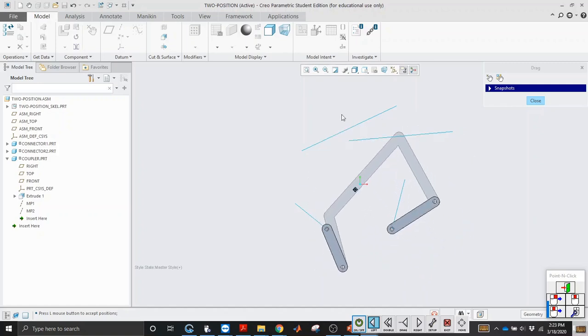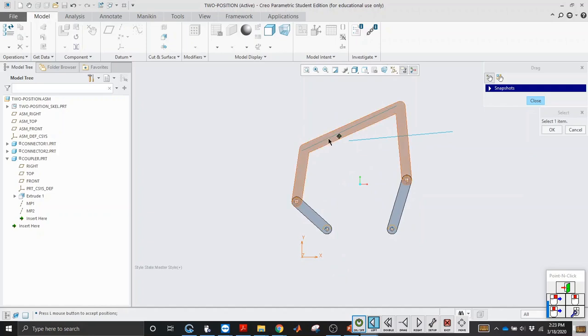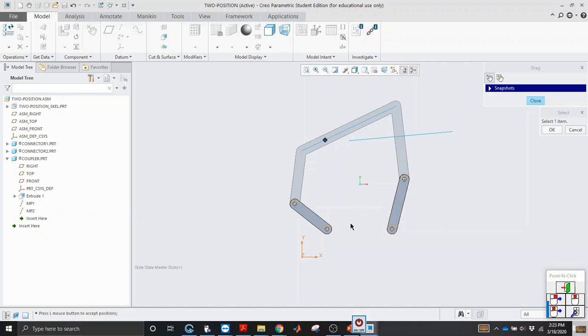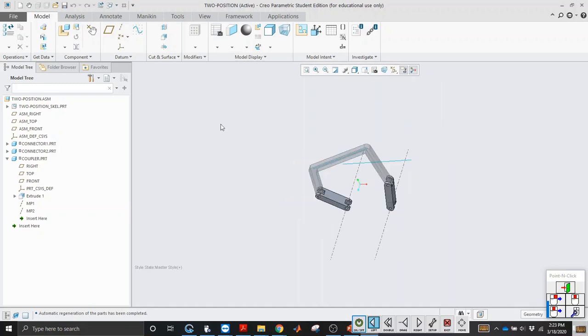It also can do a bunch of other things, and then I kind of messed it up already. But normally, this is how this Zimmerman's planar linkage synthesis using rotation angles and poles is accomplished. So you can go a step further and constrain these so they only rotate a fixed amount of degrees so you don't get stuck in this crazy rotation. But this isn't a real example, so I won't worry about that.